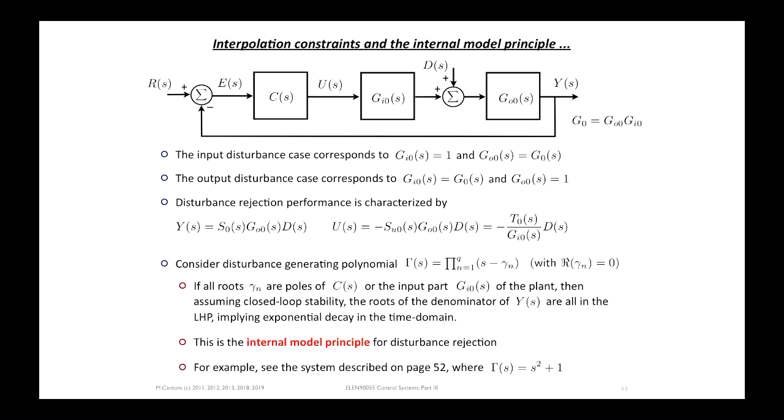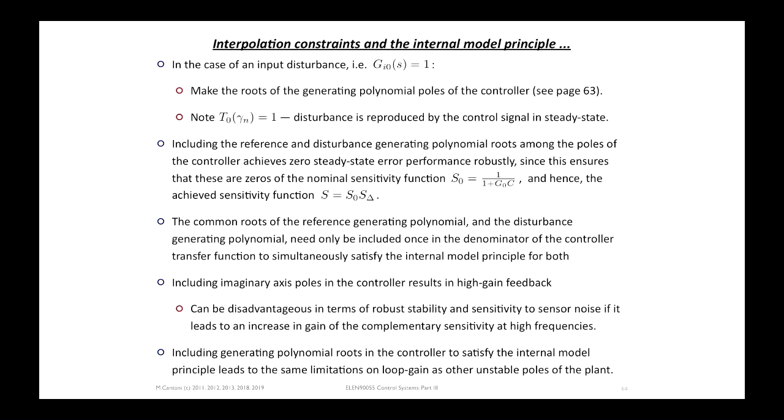And what's happening is that the control system is reproducing minus the disturbance, so that they cancel out, and you'll put 0 in here and you'll get 0 out. Making this as insensitive as it can be to this signal here. You can't be more insensitive than being 0 when you've got this input trying to push you away from 0. So this is a very powerful principle. It's robust if you put it into the controller.